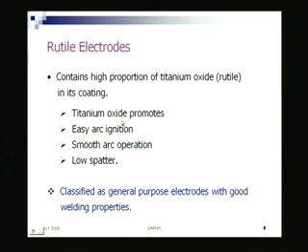Titanium oxide in the flux coating promotes easy arc ignition. It leads to smooth arc operation, which means a stable arc, and also low spatter.